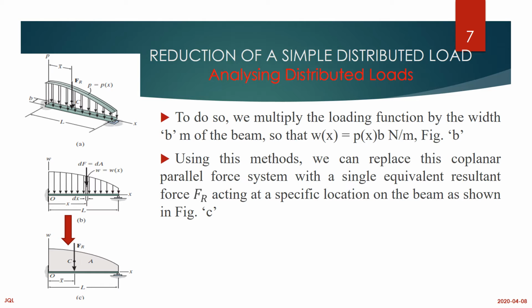Of course, to do this, you only need to multiply the function, which is w(x), times b. Using this method, we can replace this coplanar parallel force system with a single equivalent resultant force acting at a specific location, as I've already alluded.